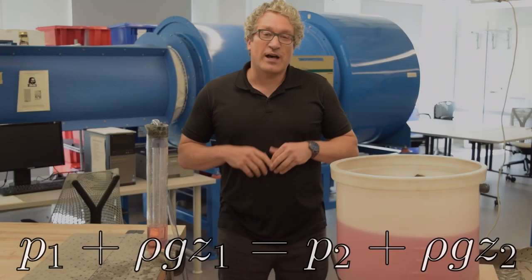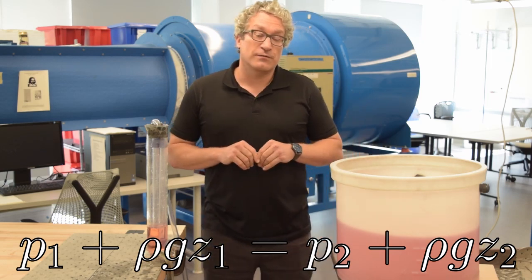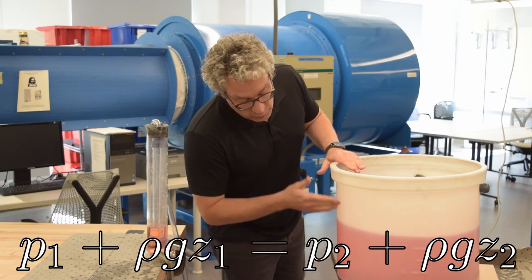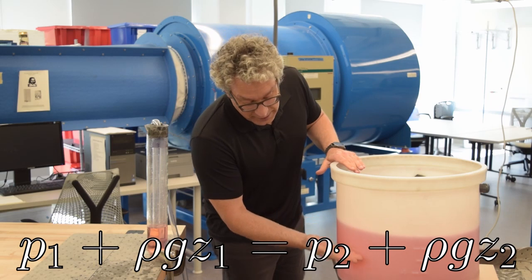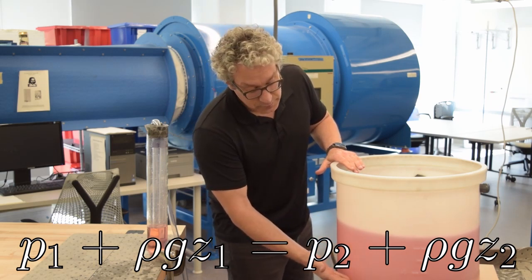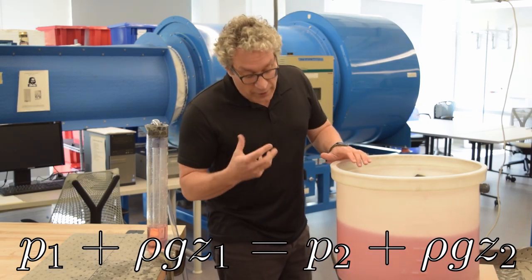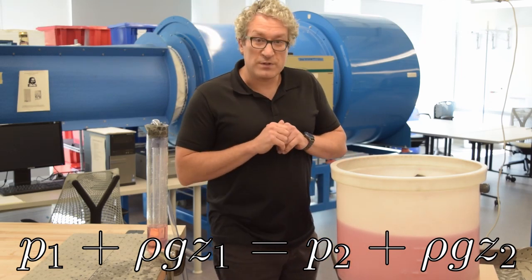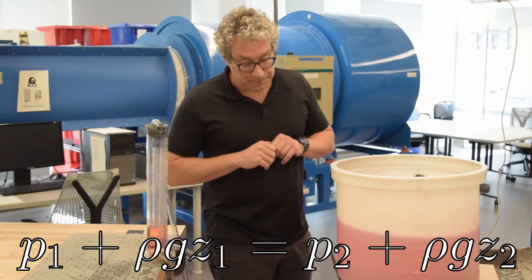The hydrostatic equation describes the equilibrium of forces in a static fluid domain. If we look at this tank filled with red-colored water, the pressure inside this water varies from the top of the tank down to the bottom. We find that the pressure is actually higher at the bottom of the tank. And the reason for that is that equilibrium has to exist between two different forces: the gravitational force that's being applied to this water pulling it down, and the difference in pressure between the top of the tank and the bottom of the tank, which is pushing up and balancing.